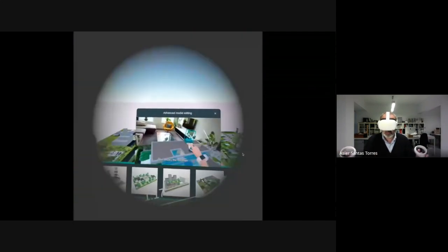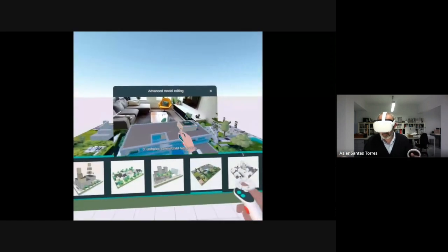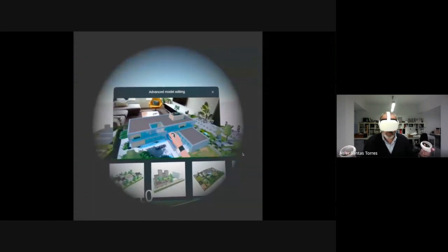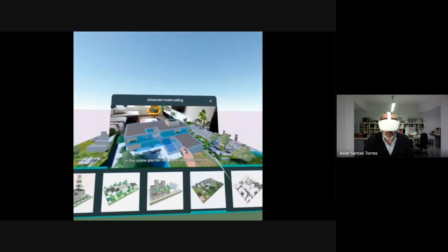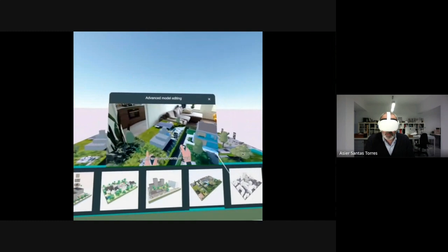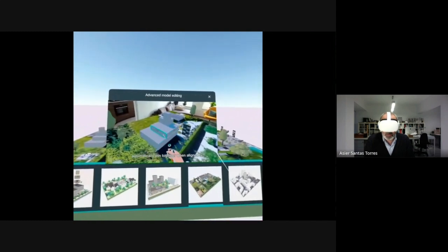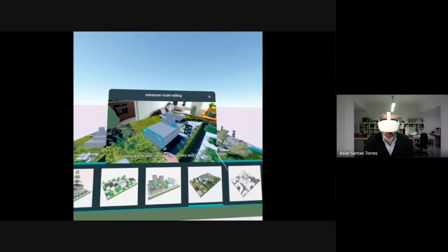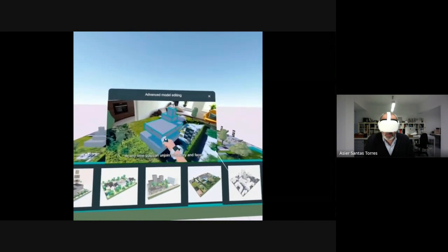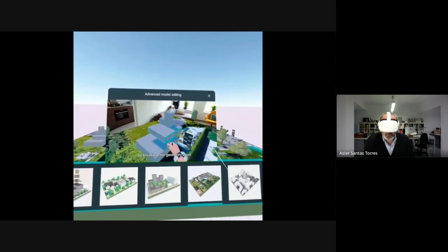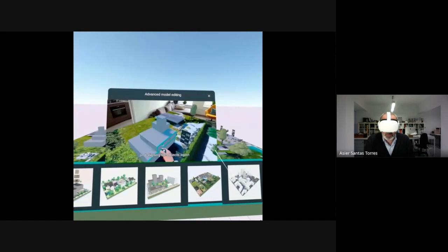Arkio geometry can be moved and hosted on any surface. This allows the creation of complex parent-child hierarchies that highlight when touched. In this scene, you can see some advanced hosting and Arkio components at work. Faces of volumetric shapes automatically join together when aligned. At any time, you can unjoin geometry and faces by breaking the geometry apart, making edits, and aligning the objects again.